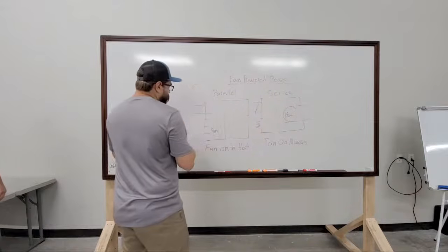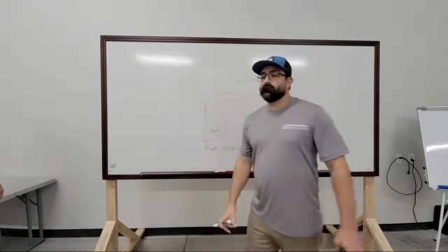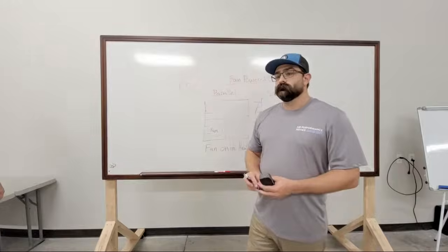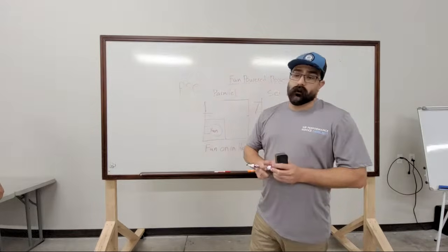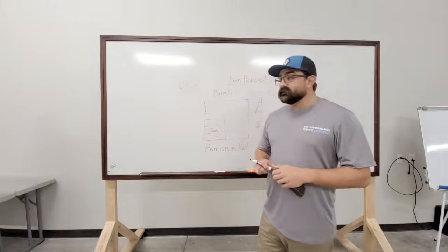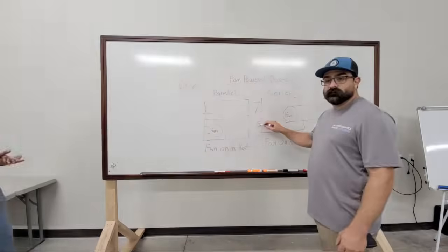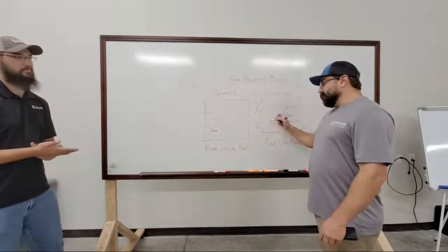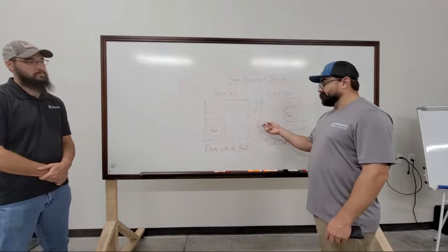PSC. So if the series fan fails, is there anything we can do before switching out to get that airflow? No, nope. I mean, you'll get some through the box, but it's gonna always take path of least resistance. And I have never seen personally a backdraft damper here.